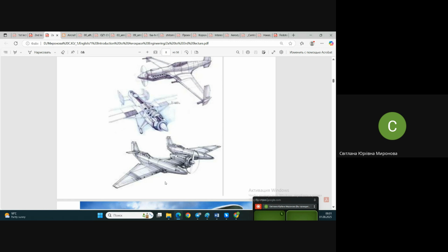And to characterize the range of speeds, that one is certainly for higher speeds than this one. It has a more blunt nose, this middle one with a blunt nose, with respect to what you see here. And here is a retractable landing gear. Landing gear in flight is absent, and this one, look, has struts, non-retractable landing gear, which creates additional drag in flight.